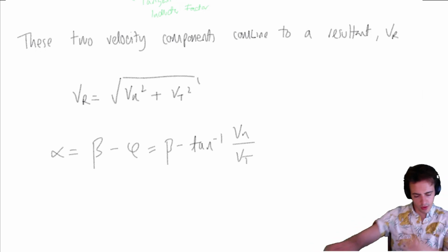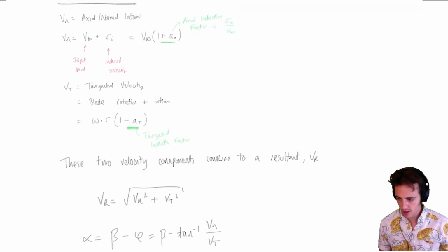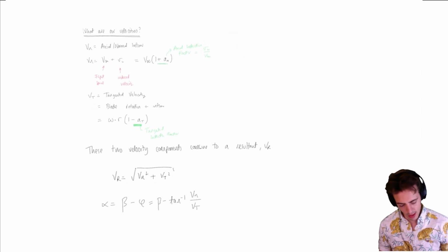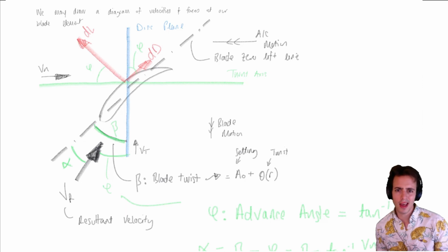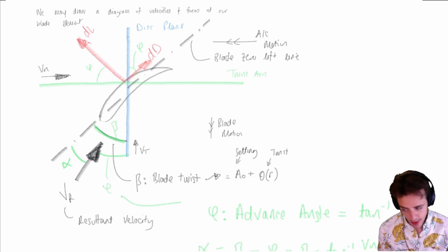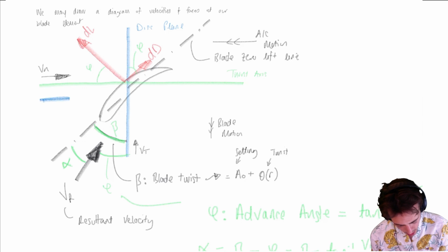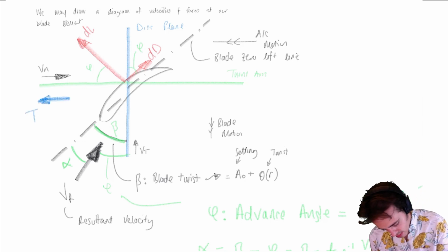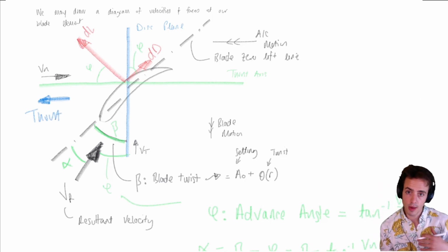So we've got the start of this model now. We've got things as we'd like them to look. Now, we've got lift and drag here. We assume we know lift and drag. And what we want is thrust and torque. So let's define some directions that we'd care to know about those two quantities in. So our thrust is any force occurring in this direction. And then torque is turning the blade around.